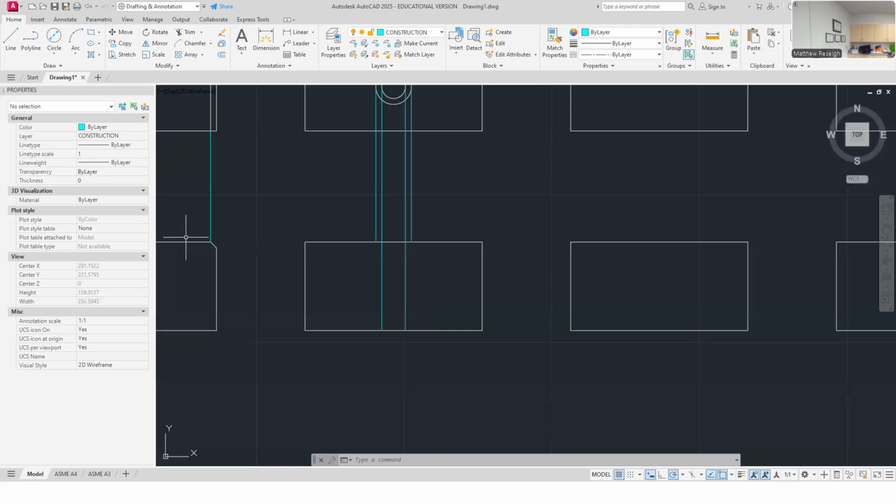Maybe it has less torque load available on the head to the surface that it's mating than that shoulder bolt does with the big counterbore. It all depends. Sometimes torque and how tight I can tighten things are based on the size. So large ones I can pass around. That is a large bolt as they come around. That is sufficient to hold substantial torque for sure. But the bevel of this head, this flathead machine screw, is what actually mates against the block.